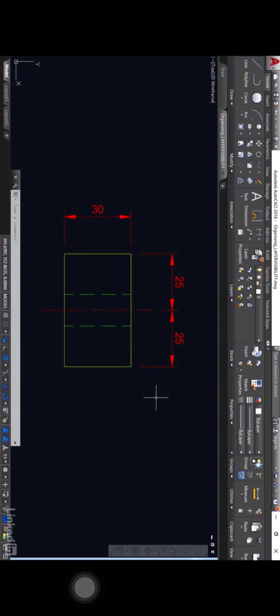Now, why do you have layers in your AutoCAD drawings? So that you can clarify the drawing and make it simpler and easier to interpret to work on the design. So, for example, it may be that the dimensions are getting in the way and you need to either freeze them or switch them off.